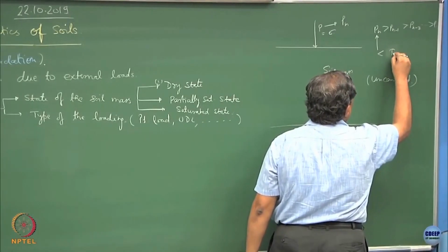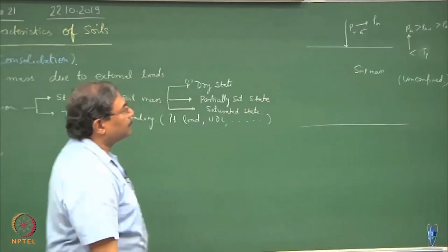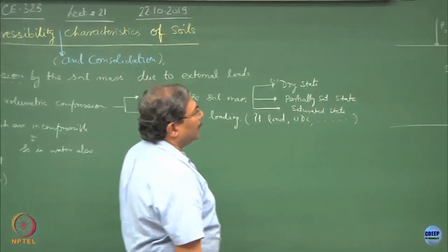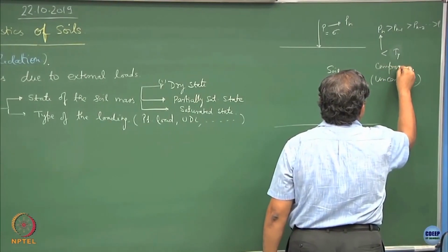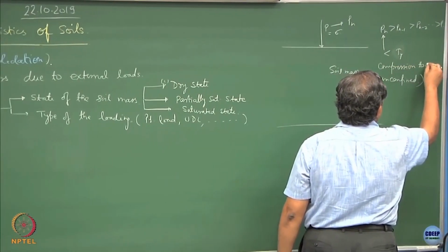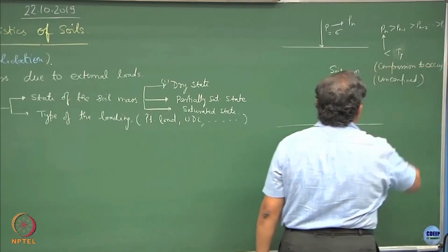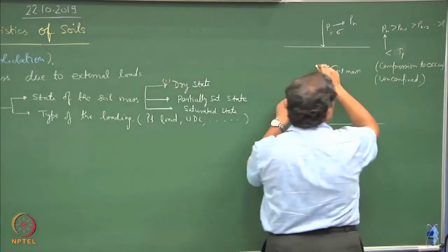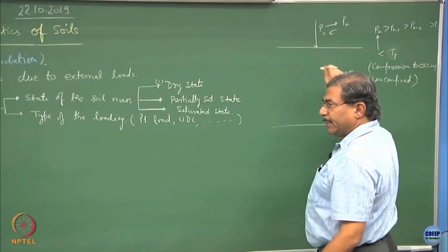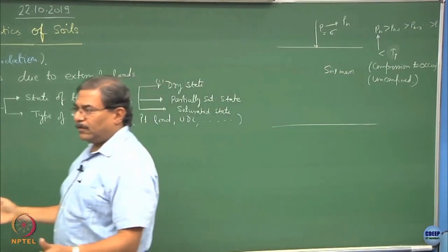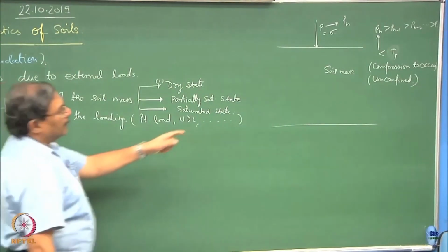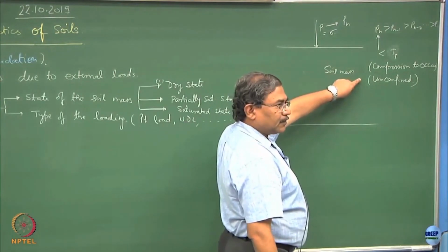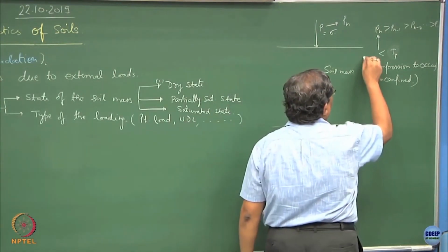So, suppose I say the shear stress y, alright. In this case, only the compression is going to take place. Why? Because the shear strength of the soil is higher as compared to the stresses which are getting delegated into it, and hence there is no slippage, there is no rolling over, there is no reorientation of the particles, and hence this is a pure case of compression. This is what we are going to study today, part A.